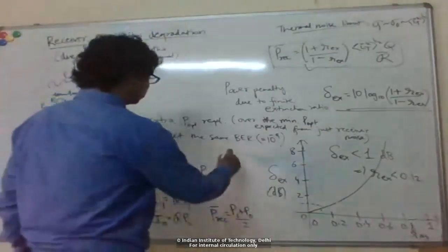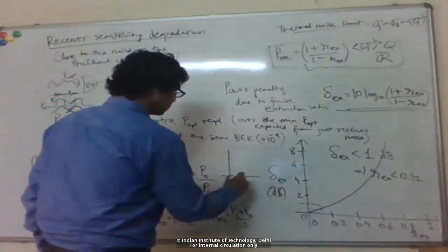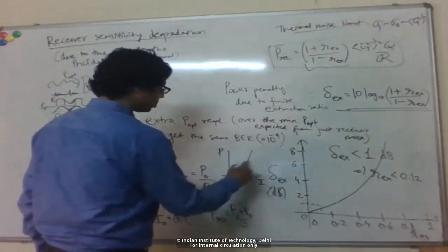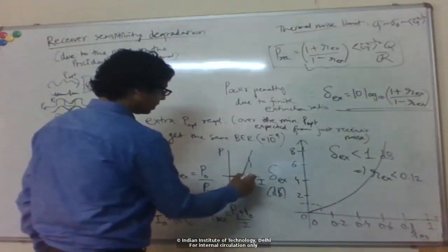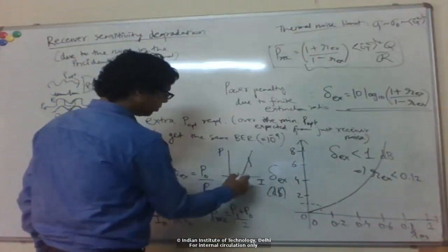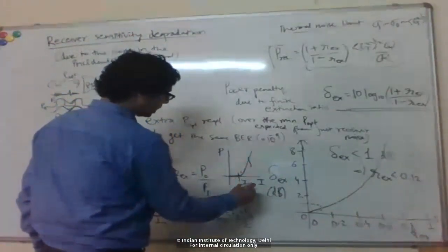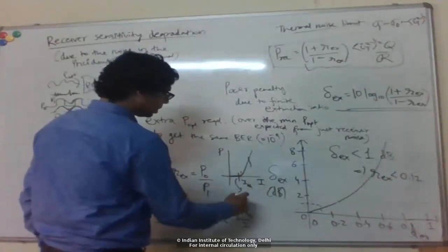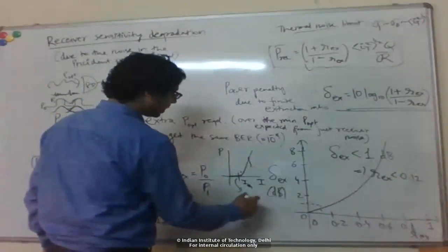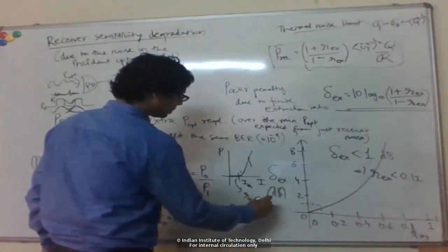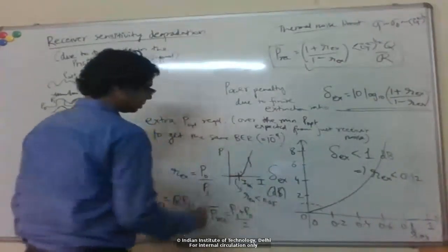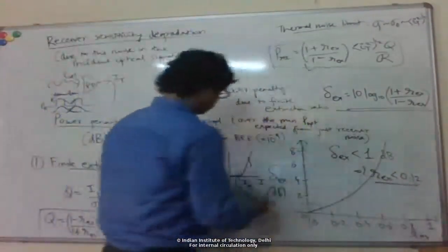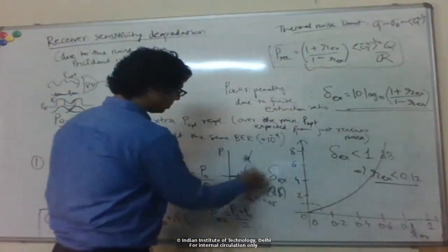Okay, and just to give you some sense of numbers here. This is the power-current characteristic of a laser, right? So for bit 0, we turn it off just below threshold. Once you go below threshold, typically this extinction ratio you can make 5% or better. So typically you can achieve this by having the laser go below and above threshold.